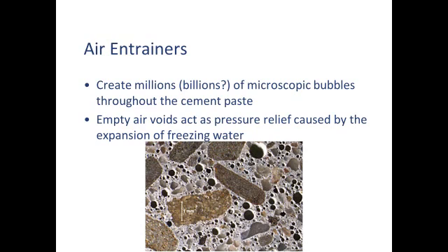When concrete's outside, it gets rained on, it absorbs water, there's voids in the concrete, and the concrete holds a certain amount of moisture. When a concrete freezes, when it gets cold enough to freeze, that water turns into ice, and ice is less dense than water because it expands. Water expands as it freezes. If there's no place for that water to go, that ice can act like little jackhammers and gradually break up the concrete.